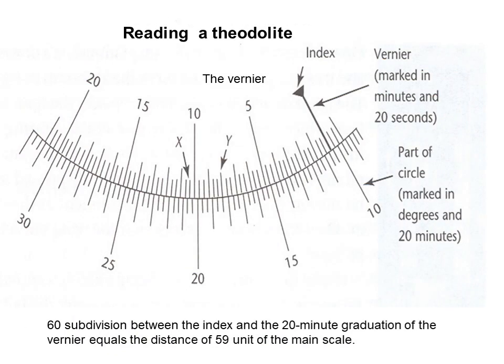Then the next type of theodolites are vernier theodolites. For reading the graduated circle, if verniers are used, the theodolite is called a vernier theodolite, whereas if a micrometer is provided to read the graduated circle, the same is called a micrometer theodolite. Vernier type theodolites are commonly used.